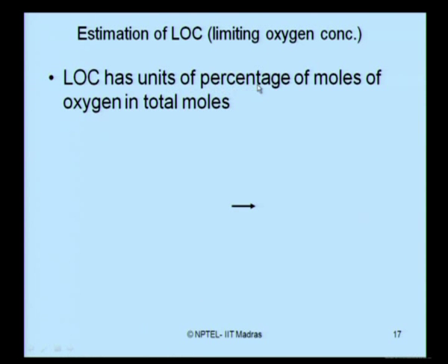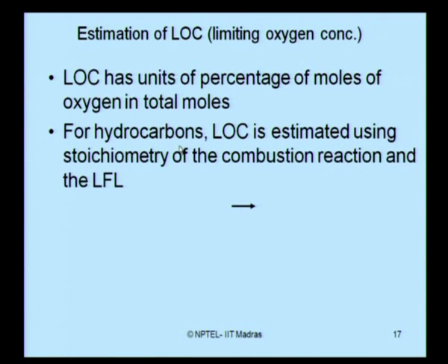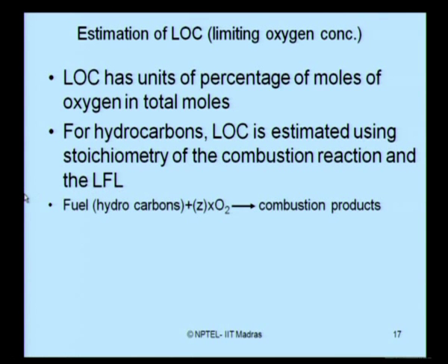One is also interested to estimate the limiting oxygen concentration of the given fuel, LOC, with units of percentage of moles of oxygen present in total moles. For hydrocarbons, LOC is estimated using the stoichiometry of the combustion reaction and the LFL. Let us say, for example, we take a hydrocarbon as a fuel and combine this mixture with oxygen, which can give you a combustion product. Then LOC is approximately equal to the product of Z, the concentration of oxygen, with LFL.